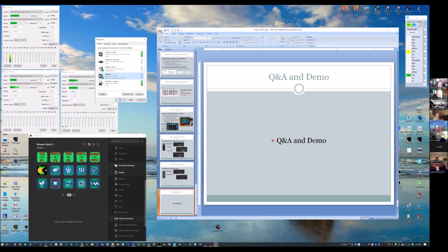I wondered if I was going to use it. It's like, oh, it's kind of neat. It's a toy. I don't mind tech, but oh my gosh, it's nuts, right? If I want to set up the radio to run FT8, I want to put it in data mode and mute this and do that. So I just press WXDT ready. Bam, it sends a whole suite of commands to put me in data mode. I have to be in N1MM running, but it puts me in data mode, does this, that, and the other thing, and I'm ready to go.